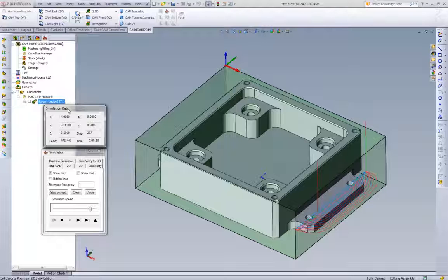When it comes to iMachining, since we actually look at how many flutes we have, we synchronize the perfect chip thickness. If you were to use a 4-flute end mill in aluminum with iMachining, you'll see that there's really no difference in feeds and speeds. Yes, when we use a 4-flute end mill in iMachining, we're not going to overload the chip thickness to that 4, 5, 6, 7, 8 thousandths chip load that we were doing with the 2-flute end mill in aluminum.